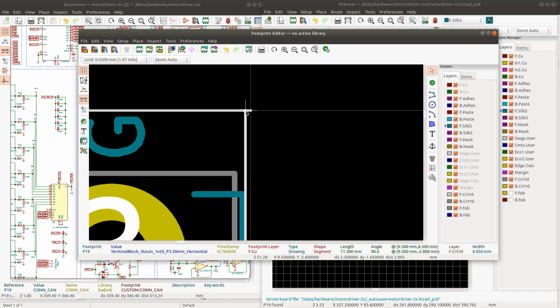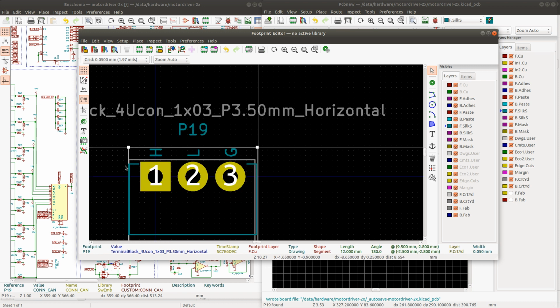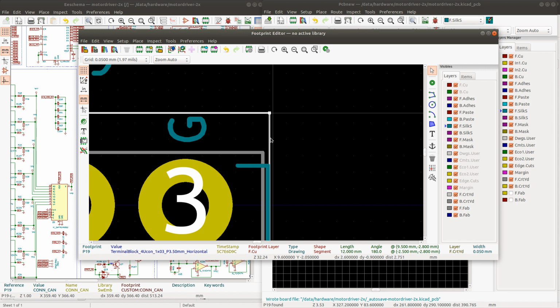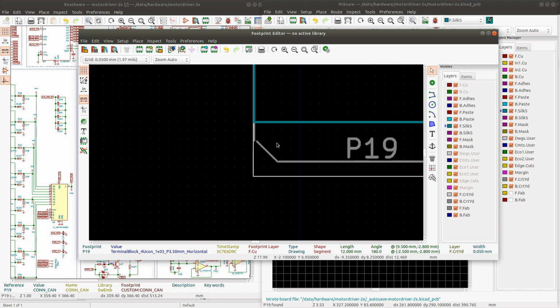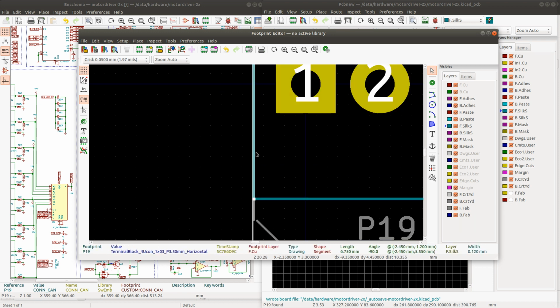So I use the courtyard for the minimum distance, and then if I violate the courtyard, because sometimes I want to do that, to place as close as possible, I use the silk screen, and therefore it's important that the silk screen is precisely the size of the component, so that I don't place them too close.